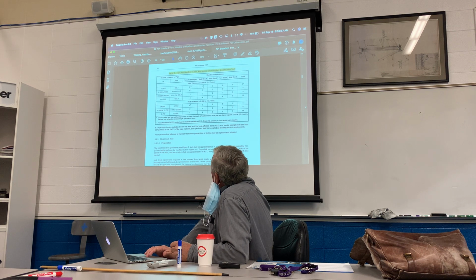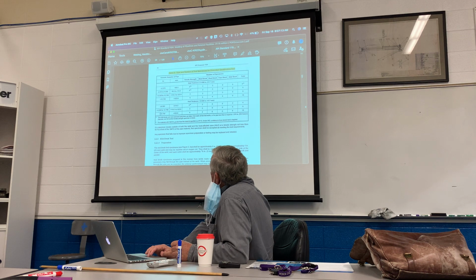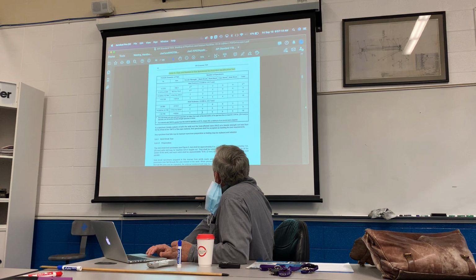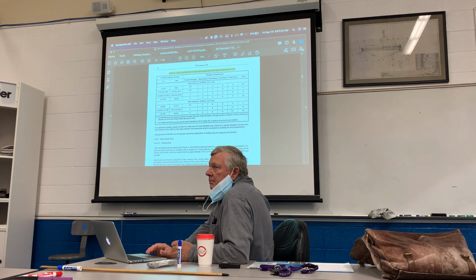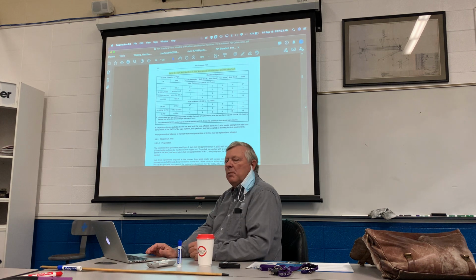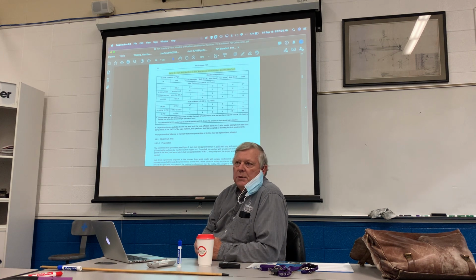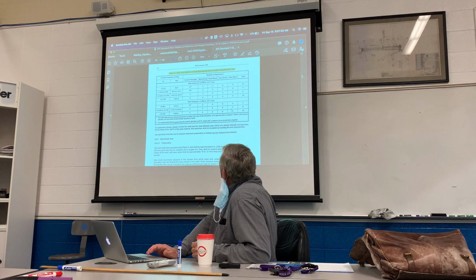Right? This top section is for wall thickness less than or equal to .500 wall, half-inch wall. Greater than half-inch wall, notice the difference in the number of straps that you pull. For 12-inch pipe, you pull 4 tensiles and 4 nicks and 8 side bends. That's usually because people don't have a bender that's strong enough to bend face and root bends for half-inch. I, however, do. I have one that can bend them.